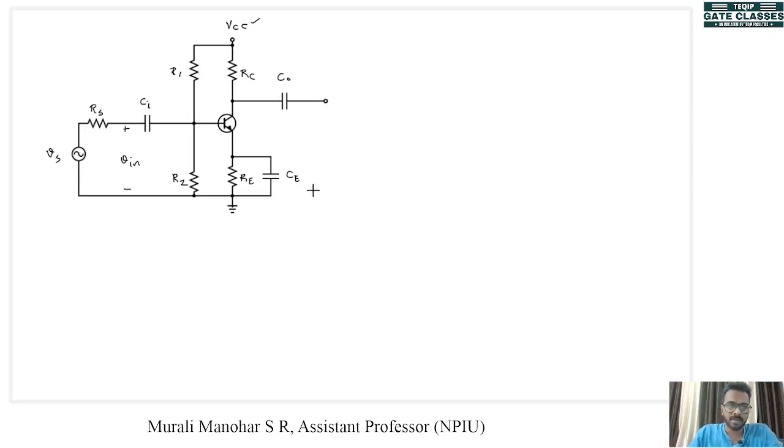For our particular application, for our particular frequency, we are assuming that this is a linear circuit. This holds for most of the frequencies or most of the operating conditions of this particular amplifier. So if this is linear, we can apply the superposition principle here, right? So there is a DC source and there is an AC source. We can separate them. We have already done the DC analysis of such circuits, so we know how to do that. Now we need to do the AC analysis.